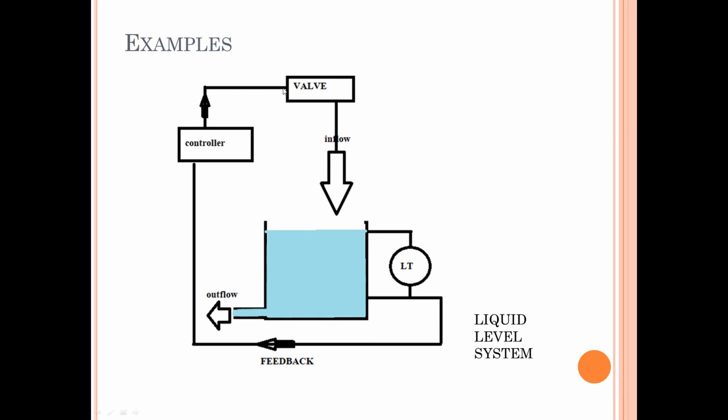The control system compares the desired level, that is the reference input, that means the 5 feet height of the liquid level, with the current level, that is the control variable, that is measured by the level sensor. Suppose at the beginning the level transmitter is measuring the liquid level as 3 feet height, so the control variable is 3 here and the reference is 5.